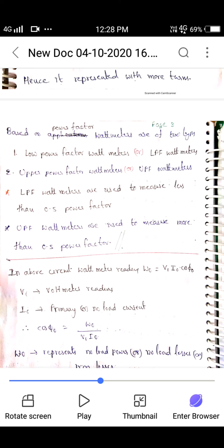Which side has less voltage means that side current is high, and which side has more voltage means that side current is less. So now we have to apply rated current, that is the lesser value. That's why we have to select the high voltage winding terminals. So at the high voltage winding terminals we have to apply the rated current.